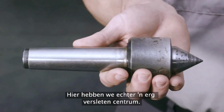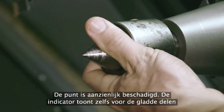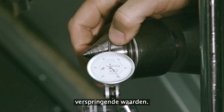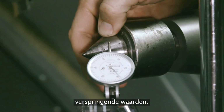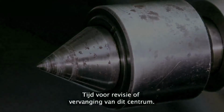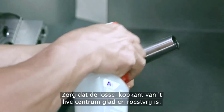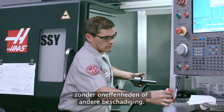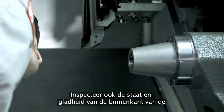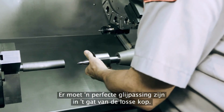it's supporting. In contrast, here we have a well-worn center. The tip has significant damage, and when we indicate even the smoother sections, we get jumpy indicator movements. These bearings and the center's tip are damaged. It's time to rebuild or replace this center. Make sure that the tapered side of the live center is clean, rust-free, and has no dings or other damage. Visually inspect the condition and cleanliness of the taper in the tailstock as well. There should be a perfect sliding fit into the tapered tailstock bore.